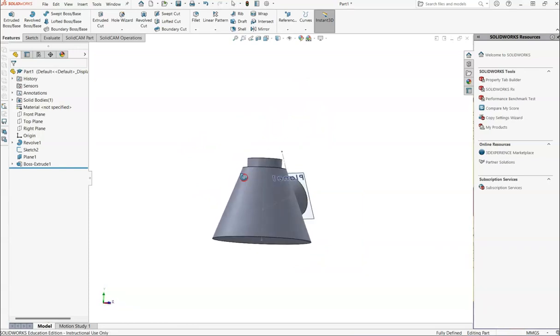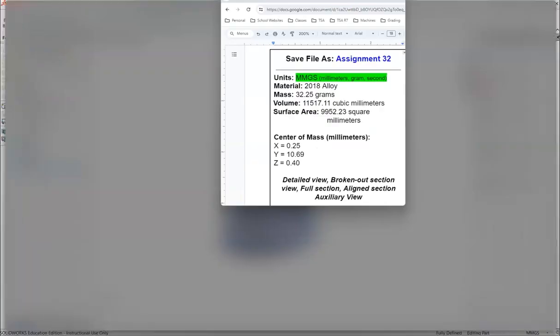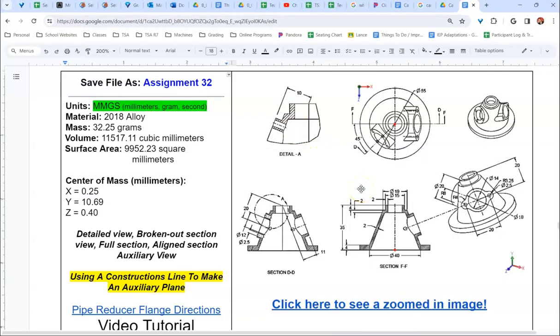But now that it's solid like this, we're going to go ahead and shell it out. And I'm choosing to shell it out now. You could do a couple other steps first, but shell it out now because you notice the wall thickness of this, which it says is 2, and 2 right here, if I follow that over and up, and this is 2, okay?